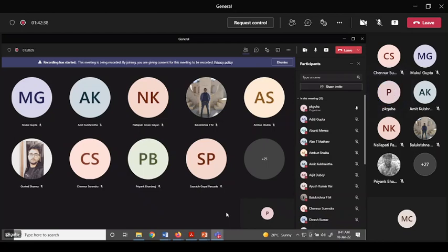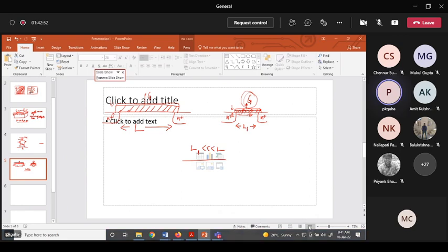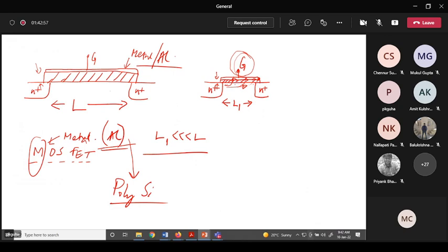Actually, we started with aluminium as gate material on top of gate oxide. Then people moved to polysilicon. So what I mean is, instead of metal we have polysilicon here. The reason being, aluminium's melting point, as your friend suggested, is only 660 degrees centigrade.